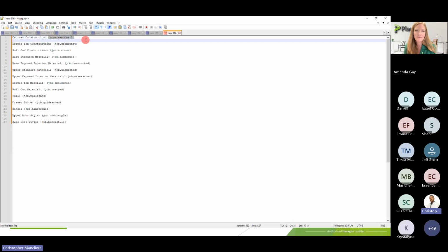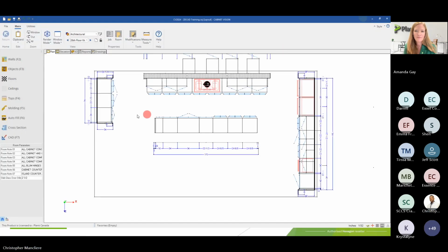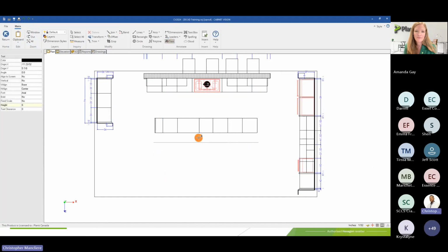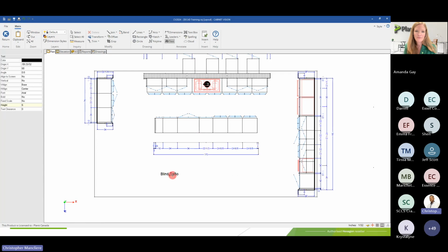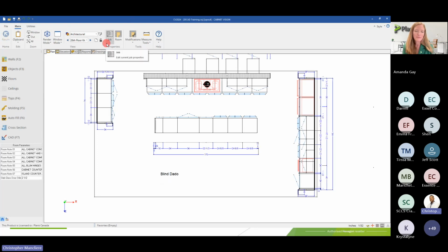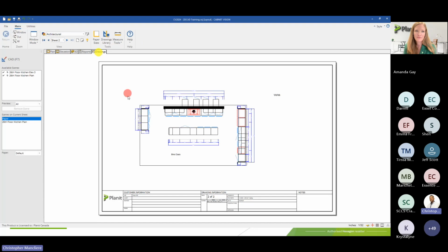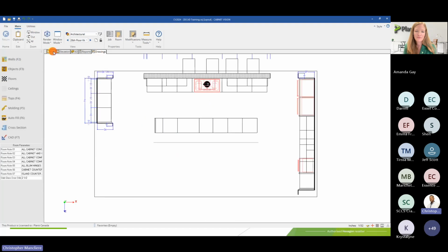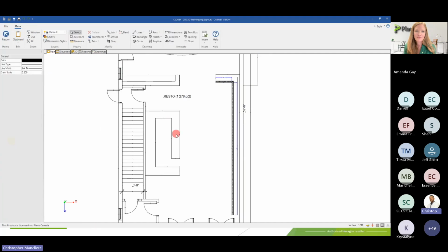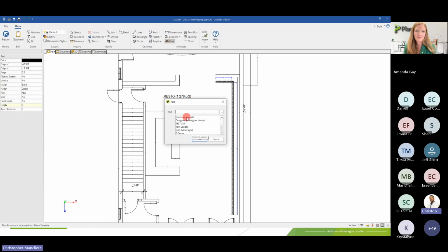So if I were to just be here and use this code and put a text, and now paste this here, click OK, that will return the construction of the room instead of the construction of the job. So if you have two rooms but different construction, you will have this now showing the construction of the actual room you are seeing on the scene. So when I go to print this, let's say I will go back to my other room and I'll put also the same text. Go text, reuse the same code.